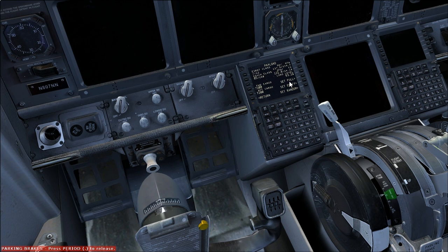And then payload. So just make sure these are both 1600. And then for this we want around 115, so you're going to add 108 to here, and then return. And next we're going to go into ground connections and just connect the external power.